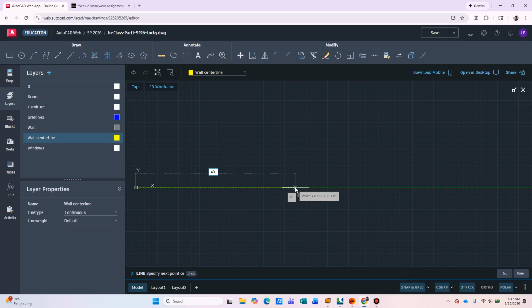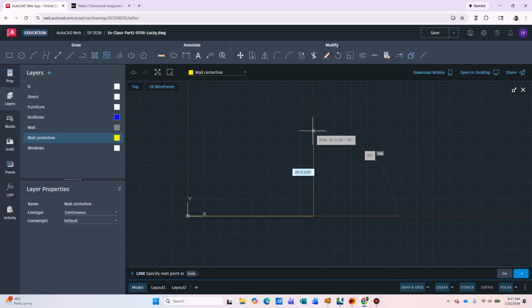Is either 40 or 30, and don't forget to add the unit. Yes. Either you can use the rectangle tool or using the line tool. And then if you want to draw it like a vertical line, just move the second point directly above the previous point and type 30 feet and continue until you got a rectangle.